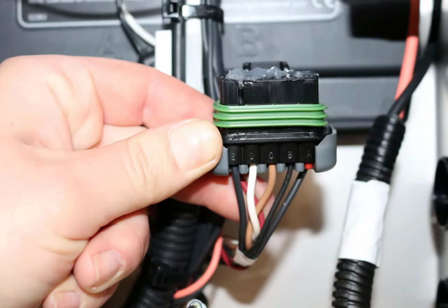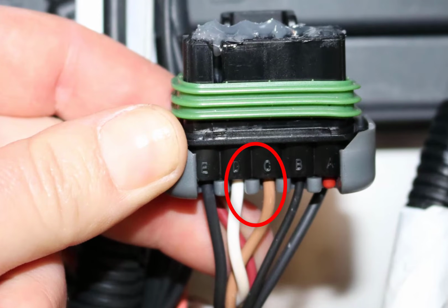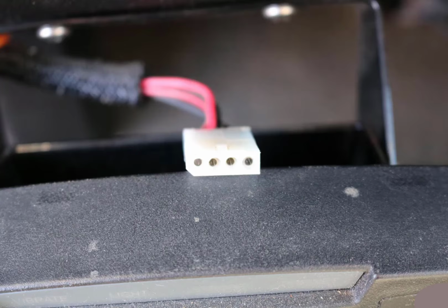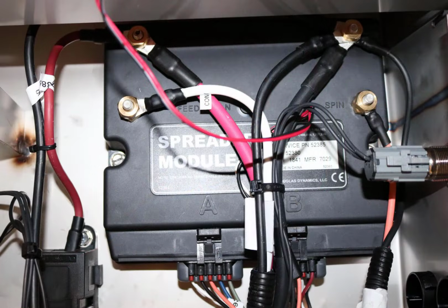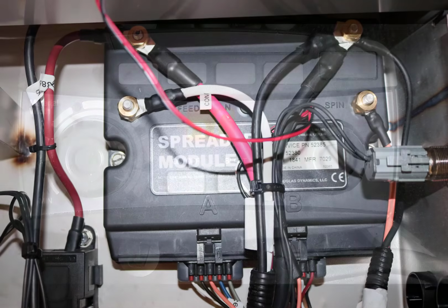Check for resistance on the white and tan communication wires. This can be done by using a jumper wire and connecting it between pins 2 and 3 of the white 4-pin connector on the control harness in the cab. Unplug the connector of port B of the module and connect the meter between pins C and D on the white and tan wire. The meter should read 0 resistance. If all the harnesses test good through all the necessary checks, it is possible that there is a bad spreader module or cab control.